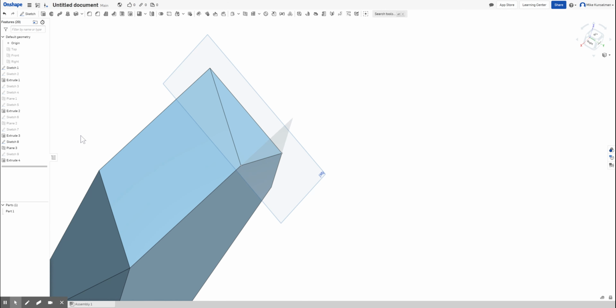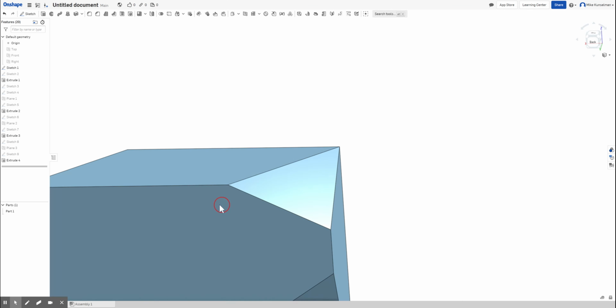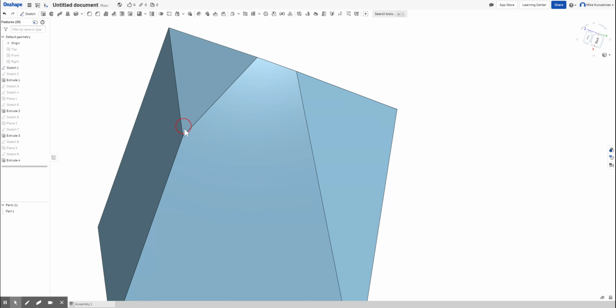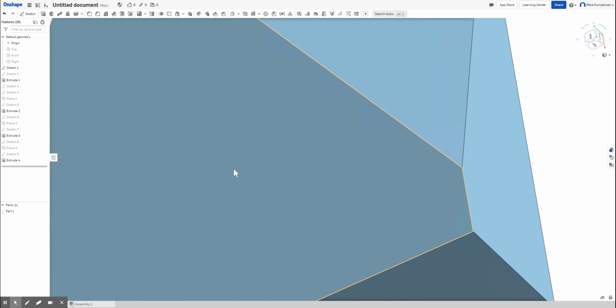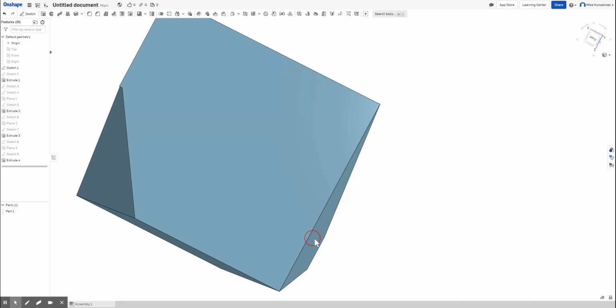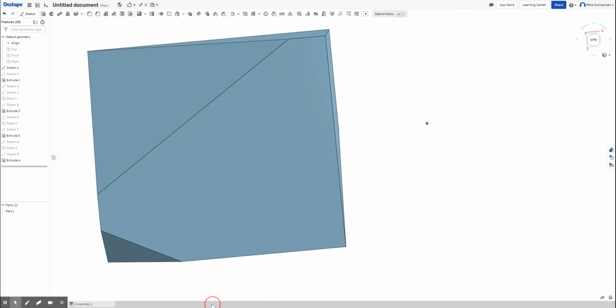Now just from a cleanliness standpoint, if you want to hide some of these ghost images in these planes, you just go over here. A lot of times whenever you see a plane or a sketch visible, like it's black, that means it's a sketch that we haven't created any kind of 3D geometry off of, which we didn't really create 3D geometry off those points. We just used the points to make a plane. So it's not a consumed sketch. Turn the little eyeball off, and then you'll see your drawing start to look a little prettier. We'll turn that sketch off. Now we got rid of those. You'll also note that I hid my X, Y, and Z planes. That's just preference. That was just a right click on the planes, and I got rid of them for demonstration purposes. I could show you that at a later date if you would like.